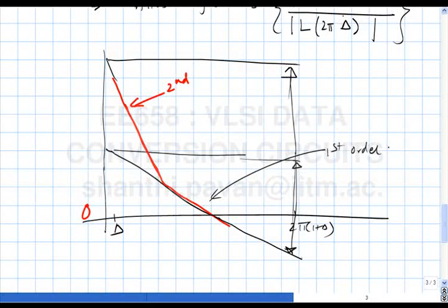And this makes sense because you have two integrators in the loop. The ratio of the gain at high frequency to low frequency will be much larger because you have two low frequency amplifiers. For low frequency, you have both amplifying. For high frequency, both integrators attenuate, so it's a double whammy for the alias.